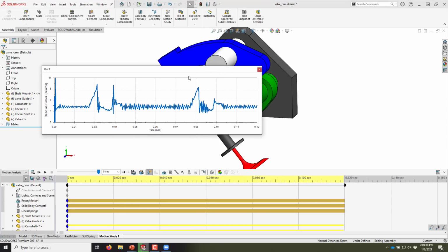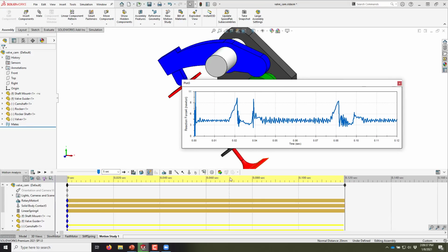Well, the way contact works in motion, it's a bit like a beach ball on water where the 2 bodies are allowed to interfere a little bit, like pushing a beach ball into the water, where it kind of interferes with the plane of the water. And so we're seeing that the 2 bodies kind of interfere with each other and they're recoiling a bunch, and it could also be due to precision of the contact.